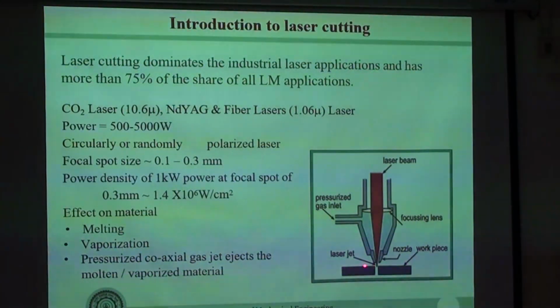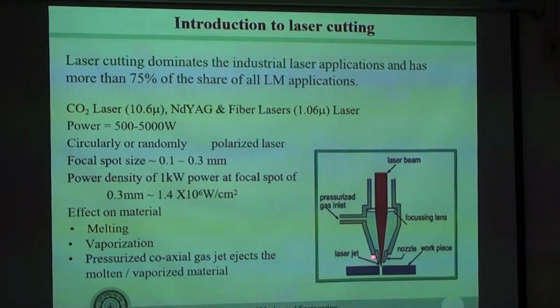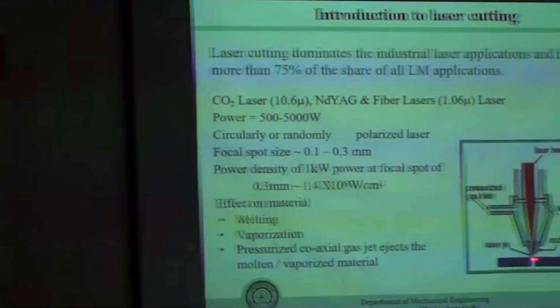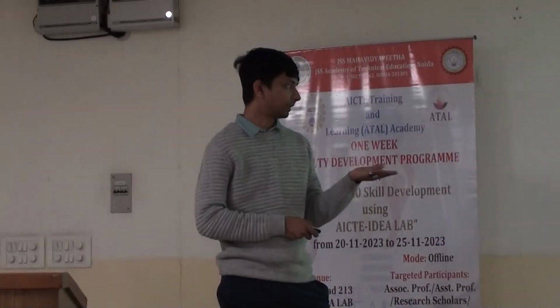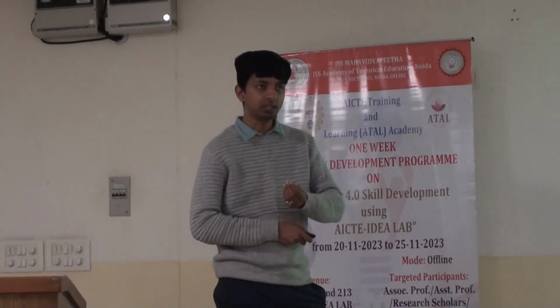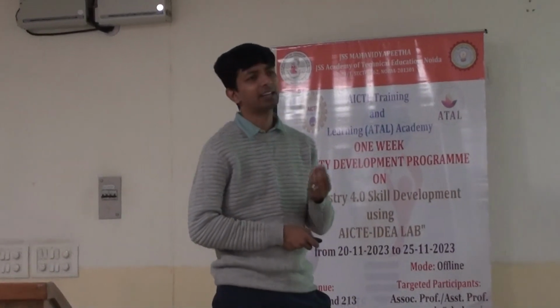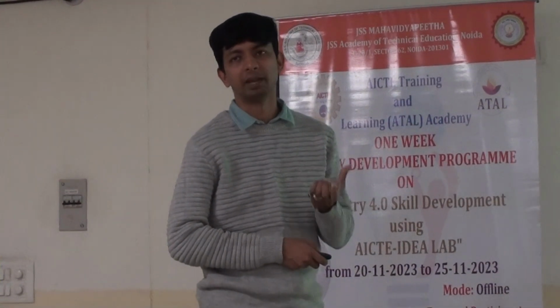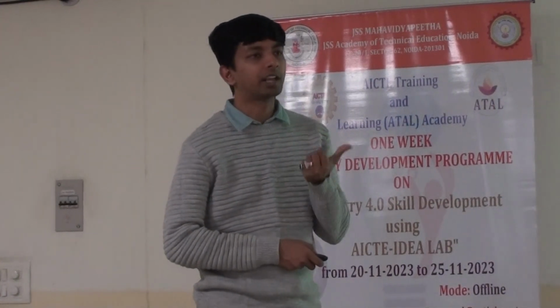By making this arrangement, what you are ensuring is that you can focus the parallel laser beam to a small spot diameter, right? And then you can mount the entire head onto a CNC, so you can move it up and down and focus accordingly. Once you ensure that, on the surface of the workpiece which you want to cut, the required energy density or power density is made. Okay? So the melting is ensured.